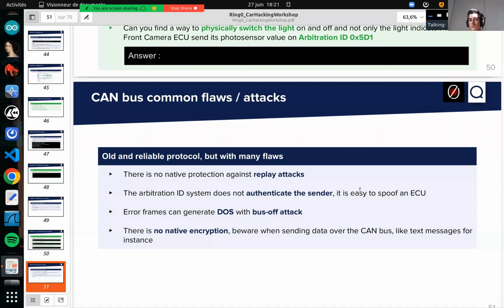It's just as if you have constant data which is not compatible with the bit stuffing part of the protocol. It will generate errors on the ECUs, and each ECU will increment its transmit error counter each time it transmits data, and will switch to bus-off. You will see on your instrument cluster, for example, that everything will turn off. You will have no information about it.